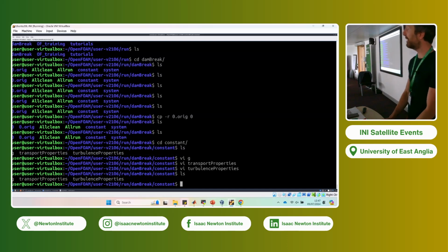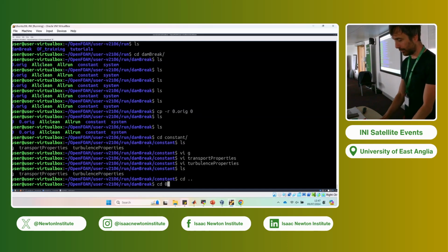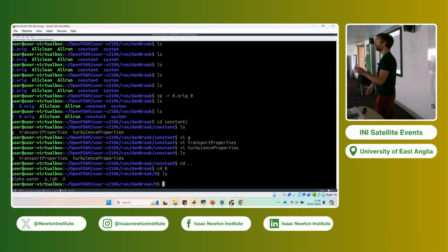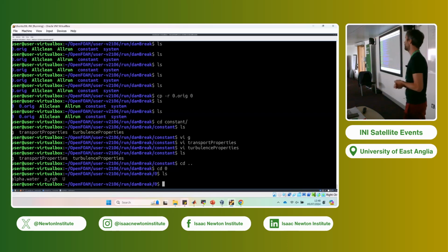So these are the 3 files under constant. Let's take a look at 0. Like I said before, 0 is where you put your initial conditions. Actually, it doesn't need to be called 0. But if you want OpenFOAM to start at t equal to 0, you need to have a folder named 0 where you put all your initial and boundary conditions. If you want to start your simulation from time 100, you will call this folder 100. Anyway, OpenFOAM will look for a folder named with a number, and that number will be your initial time.